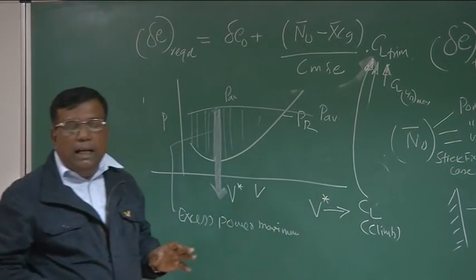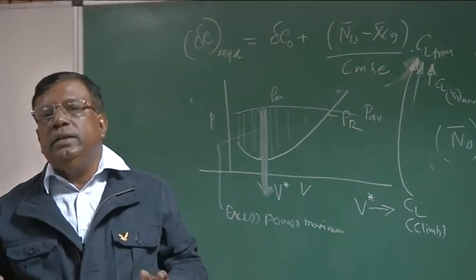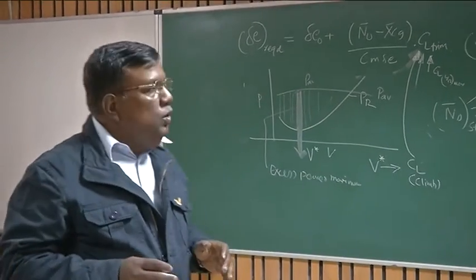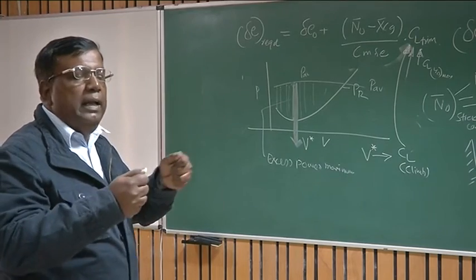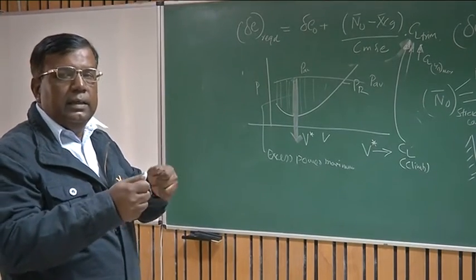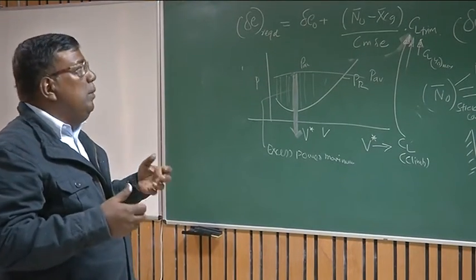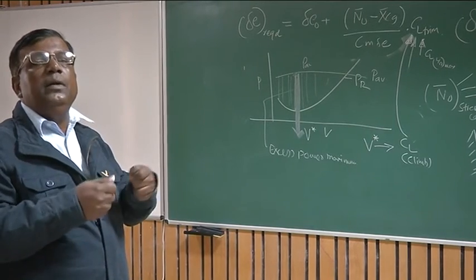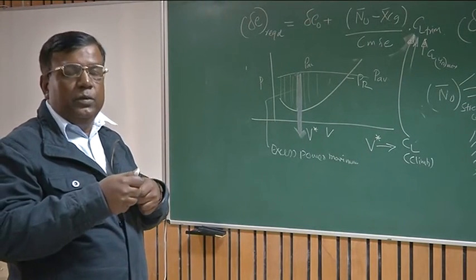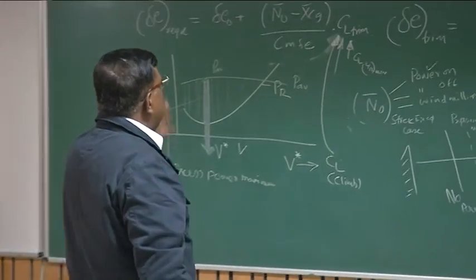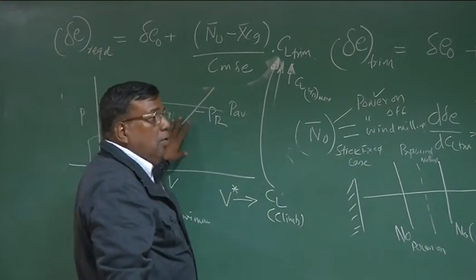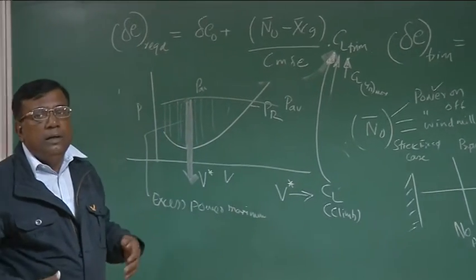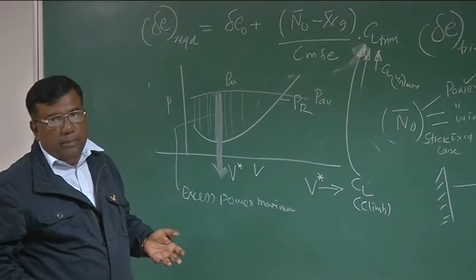Right? The pilot will not compute all these things. The designer has to see that these solutions are available. The pilot will go on handling elevator and thrust together. But if you don't have a solution in the design, then the pilot won't be able to get it through iteration. So these are very important for a designer to understand: what you are doing, what solutions are available, what sort of bandwidth you have given for the airplane.